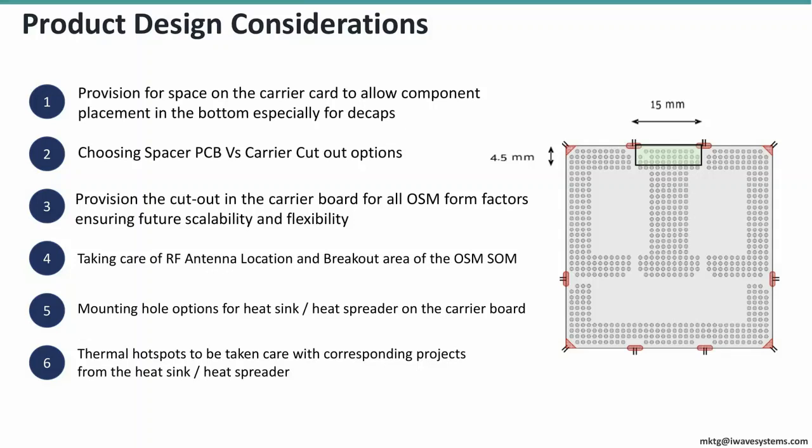And also we have seen, because it's tightly coupled, our first module, if you look at it, there is no space at all. So you have the memory, both RAM and flash, and Wi-Fi module and CPU and the power management area. So the hotspots were quite high, right? So it's better to plan initially itself with a proper simulation and bring your heatsink and heat spreader designs in the starting phase itself and provide sufficient spread out areas, so you make sure that the entire SOM is properly thermally managed.